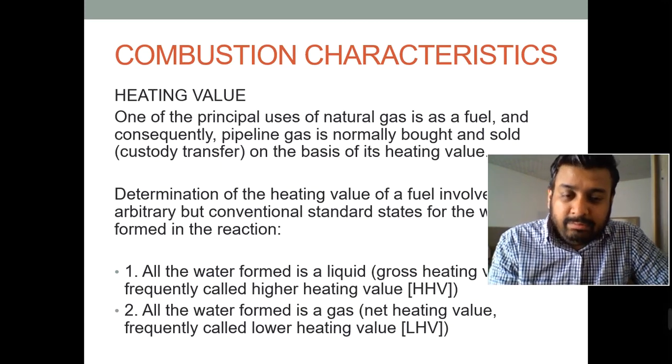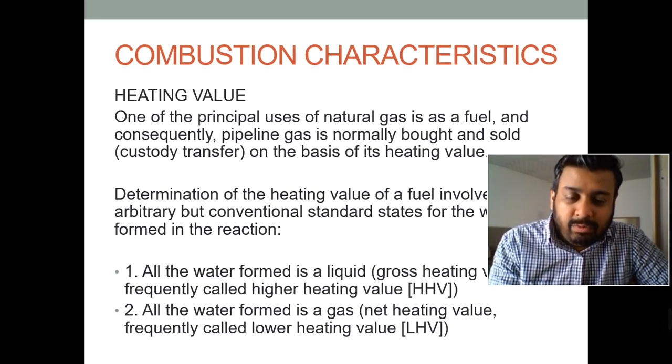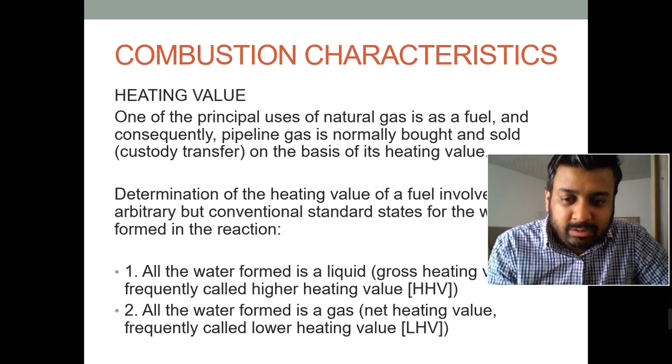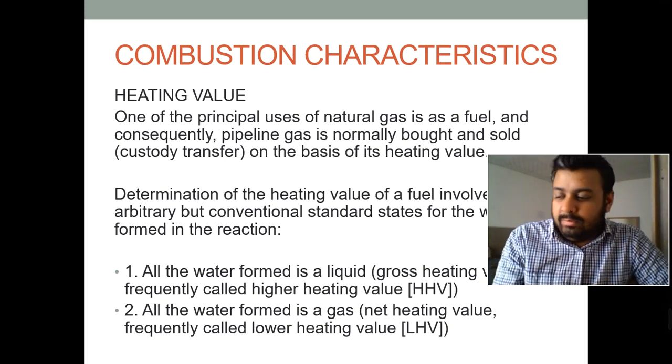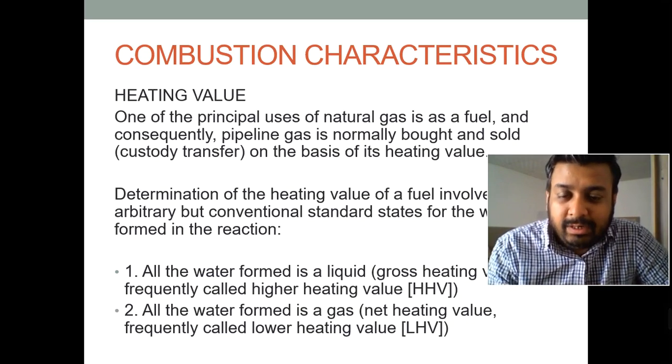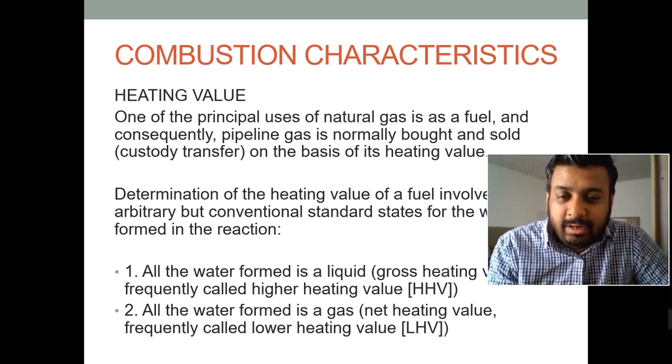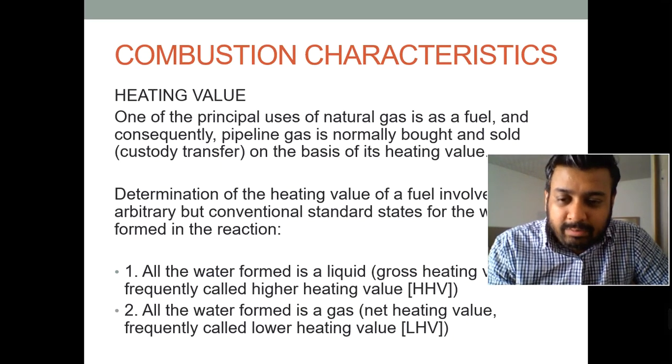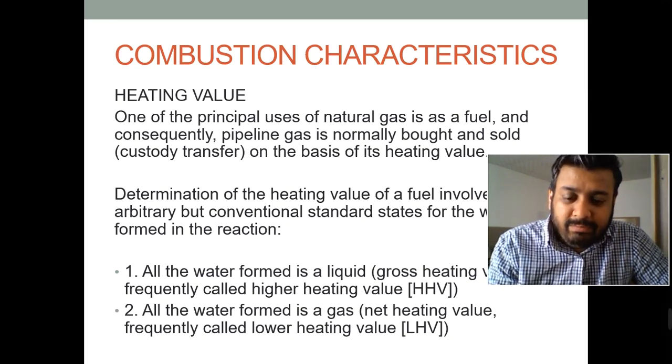If you cannot provide them a high heating value gas, they will not accept it, because they cannot maintain the temperature they need. That's why the high heating value and lower heating value are very important when we sell the gas.